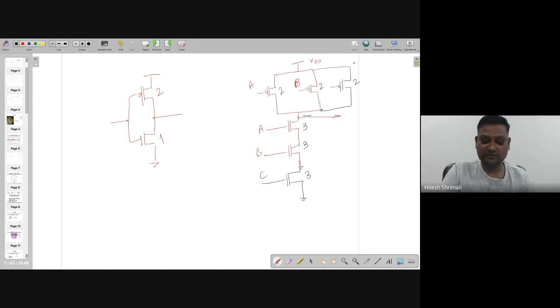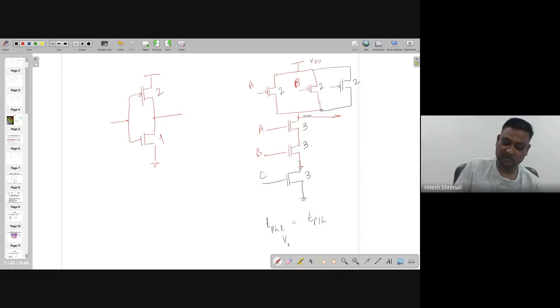All these numbers are very important when we find the logical effort or the electrical effort, because C in and C out depend on these values. This has to be designed in such a way that you are designing an inverter where TPHL and TPLH are equal, or the switching threshold is exactly at the middle. This is possible when you use such a ratio. Otherwise, this is not going to be achieved. So we expect that we make the W by L of any logic gate like this.